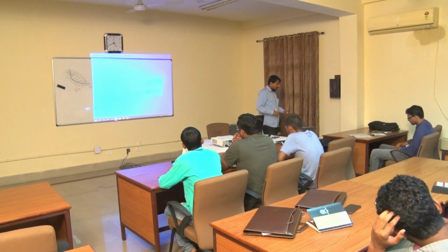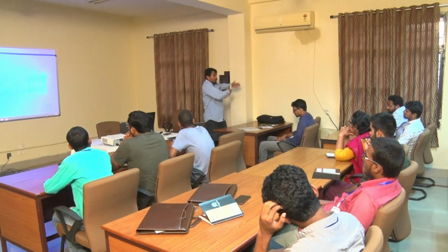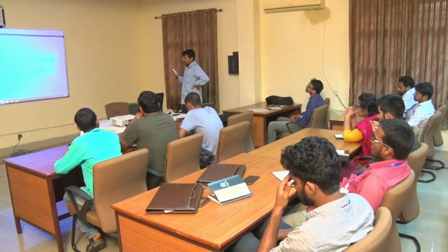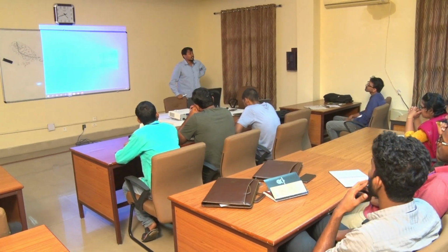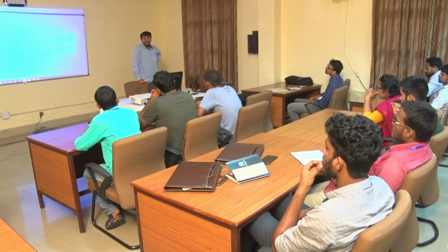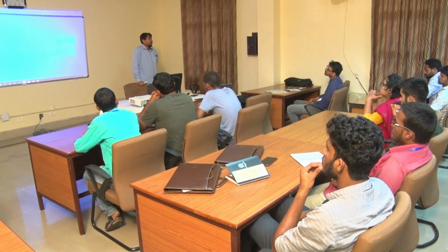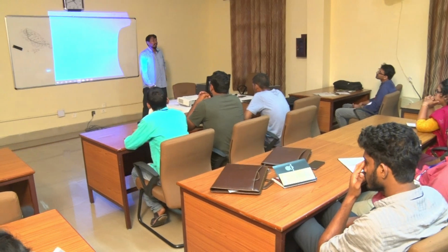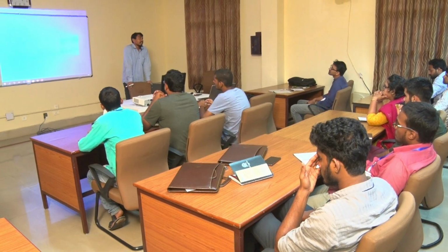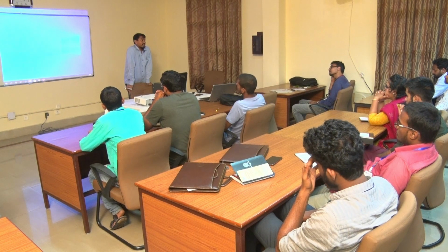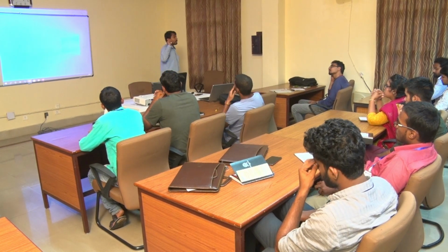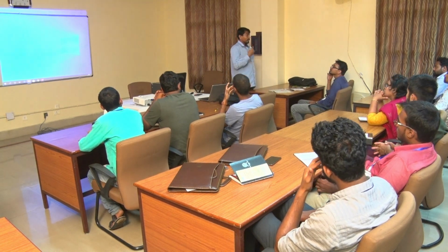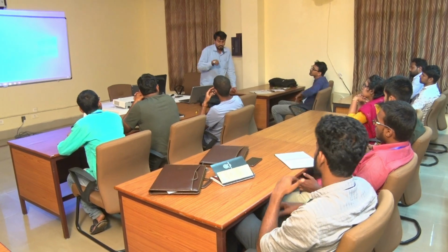So what we do in this case, we generally segregate rock and soil separately, and we try to find the amount of composition of the soil in this kind of dark material, and then we try to characterize the soil using ASTM methods only. Look at how they prepare the sample for testing direct shear as well as for the triaxial setup. That is why I have shown you some samples of the triaxial setup, and we observe a true shear plane. And you need to take care of that when you prepare that kind of soil sample.